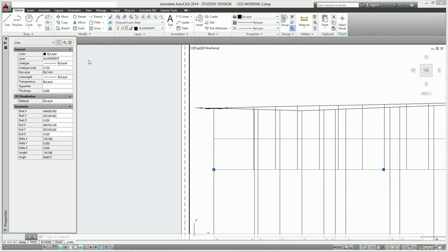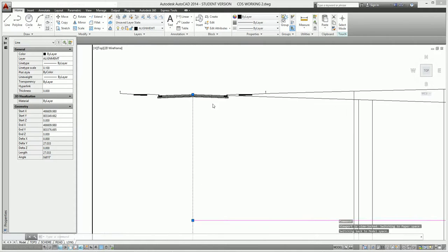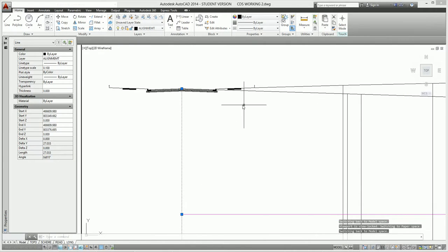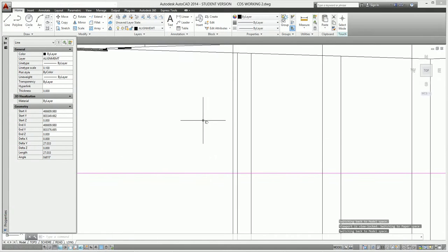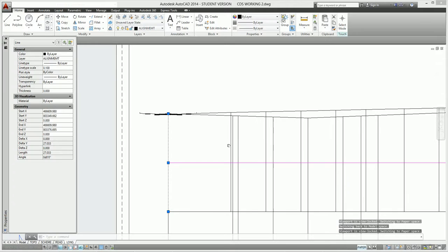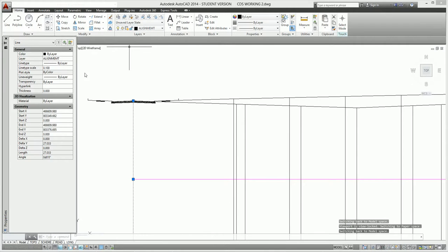So the first thing I've done is put that onto single capture. I've just plotted in here this distance 27.033, which you'll recall is the calculated level of where we're going to come off the existing centre line. Then I made a copy in here of my typical cross section and put that in there, like so. So now it remains to work through and put in the surface.